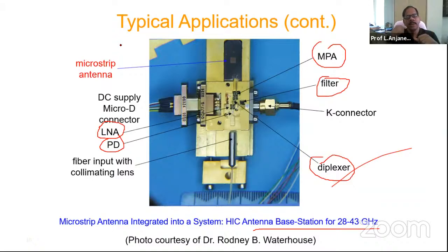But depending on the application, as you see, there are various wireless applications. So depending on the band of interest, we have to choose an appropriate material for microstrip designs, for the microwave and millimeter wave designs, and we have various materials available in the market. Some of you may be doing research in antennas, or some of you would have already completed your doctorate in antennas and microwave engineering. So they will know that materials like RT Duroid is one material, and FR4, fire retardant 4, and like that. There are various substrates that we get for designing microstrip antennas, and various thicknesses.